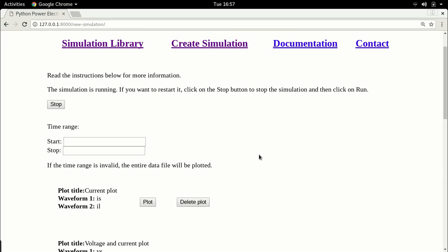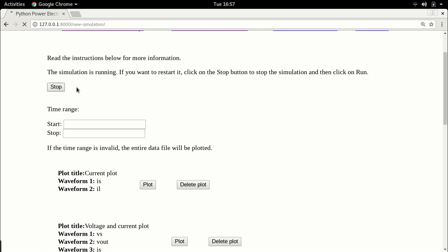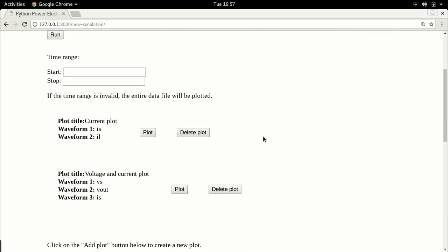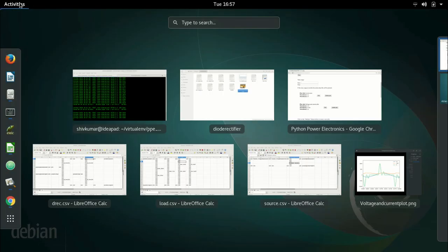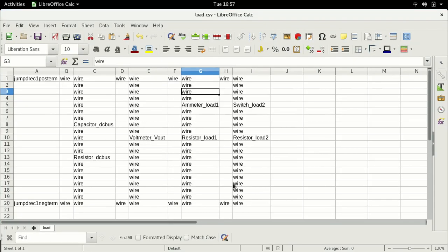As I said before, there is one resistor connected constantly at the output of the diode rectifier. Another resistor is connected through a switch. This switch is always open, so that resistor is never connected. But now we're going to switch this resistor: turn it on, turn it off, turn it on, giving it a duty cycle. I'll show you how we can control this switch to run at such a duty cycle. That will be the next lecture.